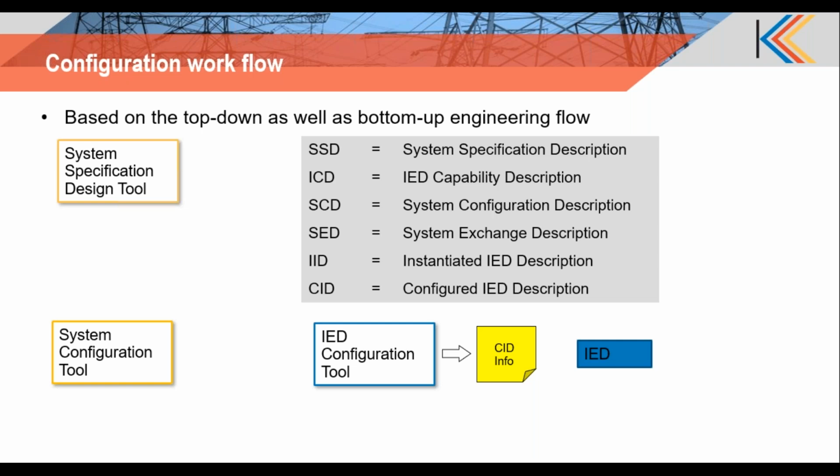Interoperability gives a provision of seamless integration of information exchange between devices that are provided by different vendors. So here you can see there is a system design or system specification tool, and then there is a system configuration tool. These two tools are actually independent of the vendor. They can be provided by the vendor itself, but these tools should have open interfaces by which they should be able to ingest different SCL files generated by different IED configuration tools.